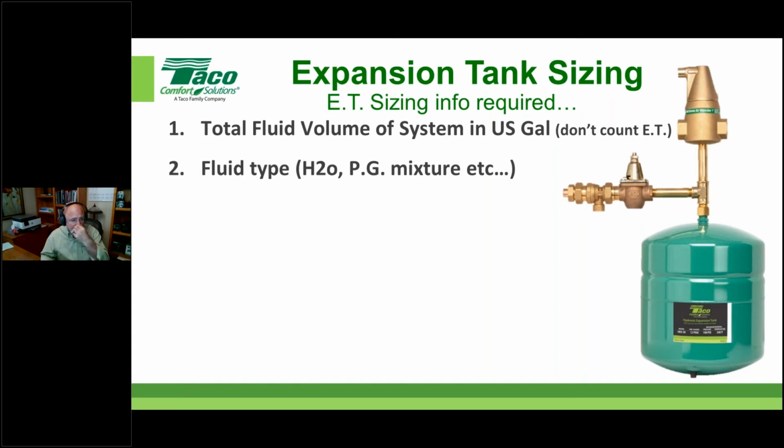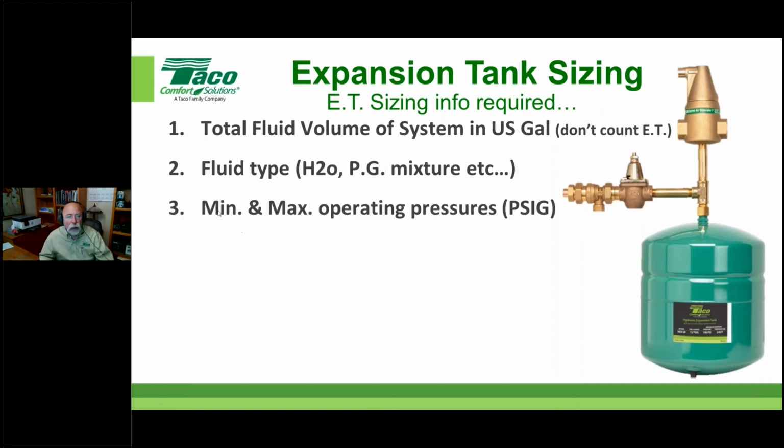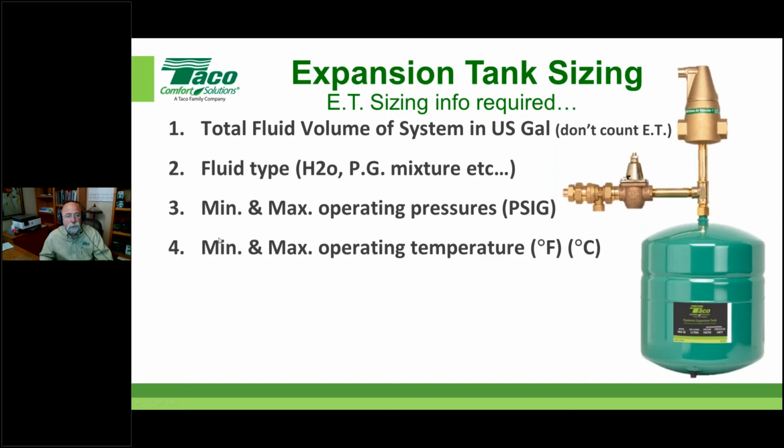And we need to know something about that fluid. We need to know whether it's mixed with anything like propylene glycol, or is it just good old H2O? Okay. We need to know what the minimum and maximum operating pressures are in PSIG. Okay. Minimum and maximum operating temperatures. Okay. We need to know what that is as well. And the relief valve rating.